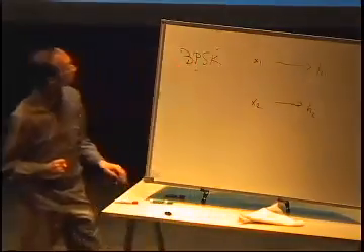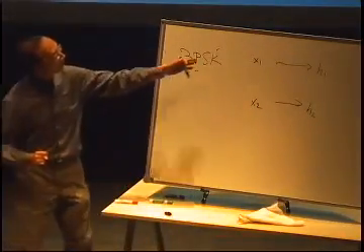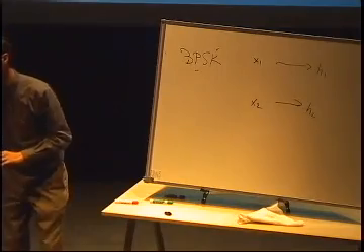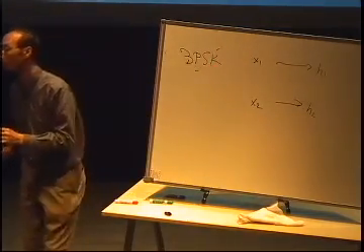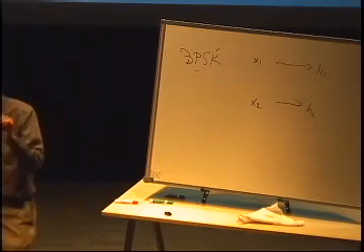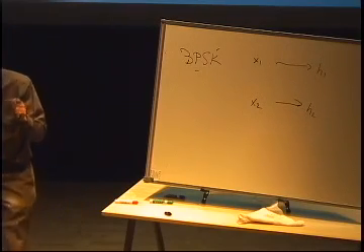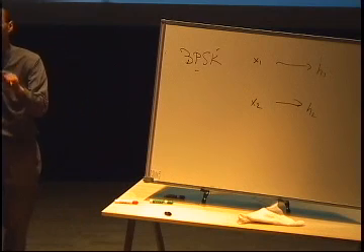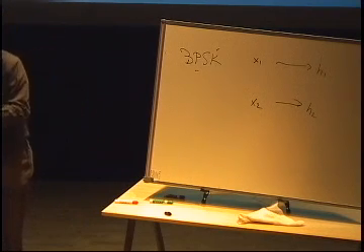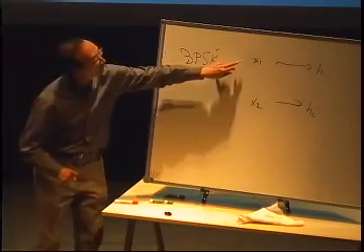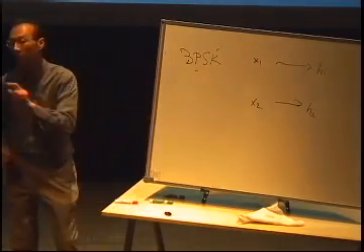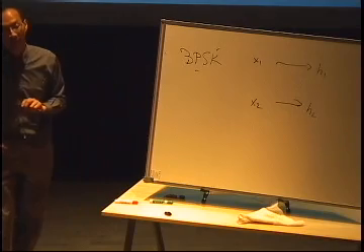OK? Now, in the case of repetition coding, what we're doing is we're sending X1 and X2 to be the same symbol. And therefore, we can only convey 1 bit of information over 2 time slots. So our data rate is slowed down by half into half bits per symbol. Now, what we want to do is send 2 independent symbols to get back the 2 bits.